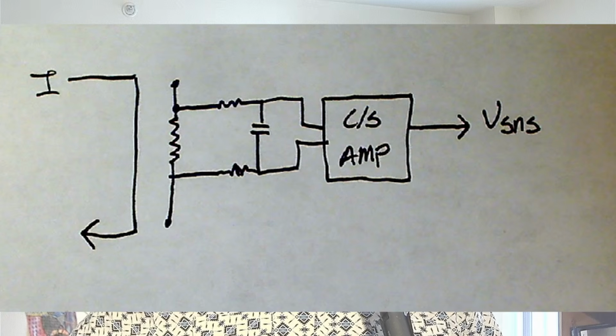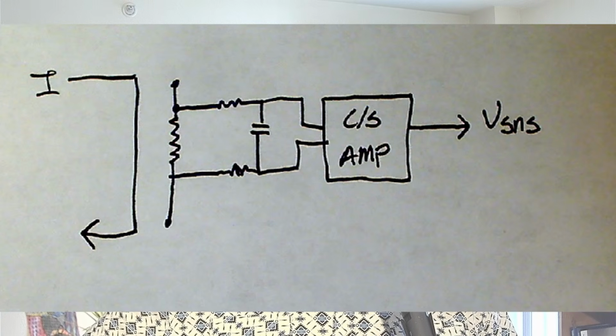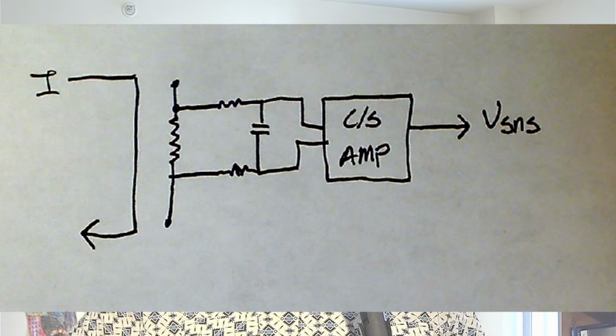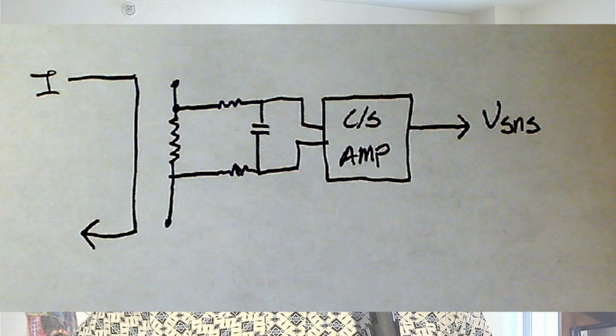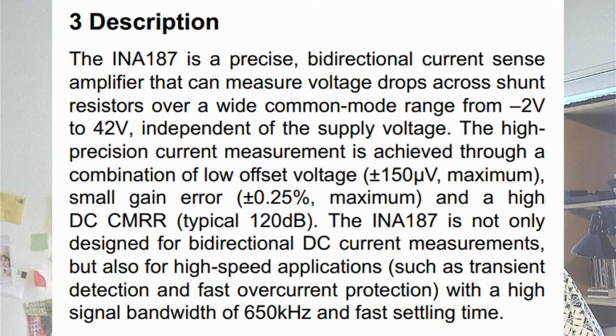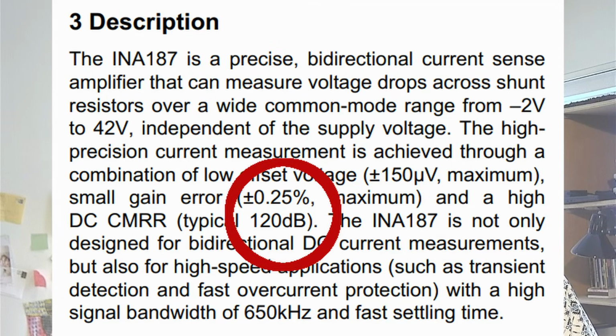Another example very quickly is a current shunt amplifier. Sometimes you need to sense the current in various places of your circuit. Well, a current shunt is one way that you can sense that current. A current shunt is just a resistor. That shunt is just another name for a low value resistor. We're talking 1 milliohm, 10 milliohms, something small. And the reason that you might use a current shunt amplifier is because it has very, very good common mode rejection. And it has very good differential amplification.